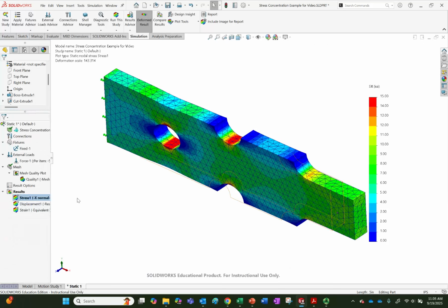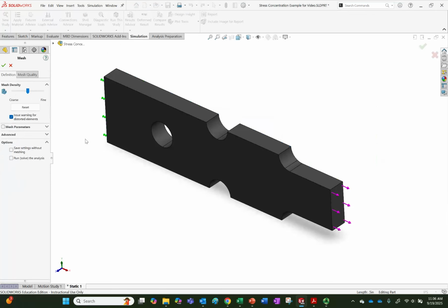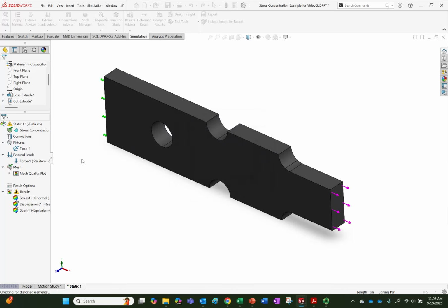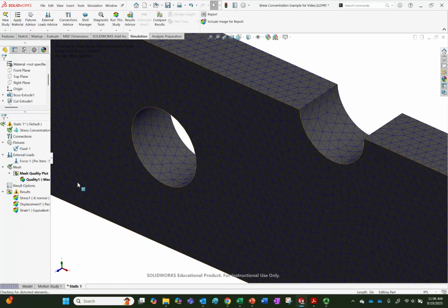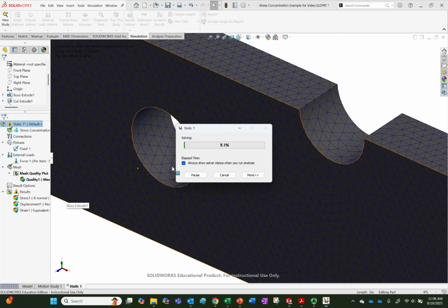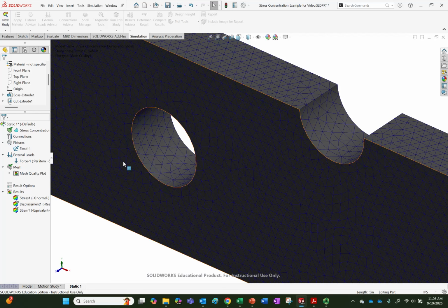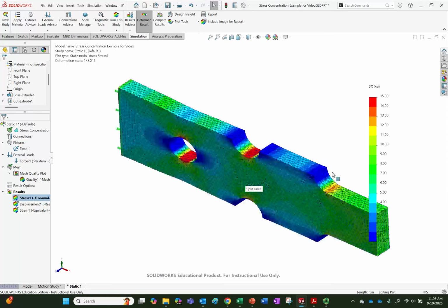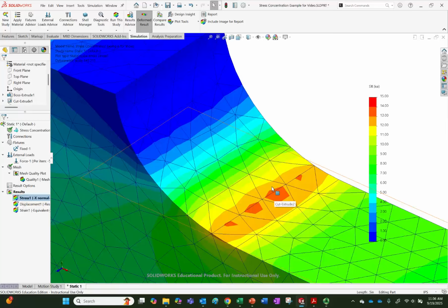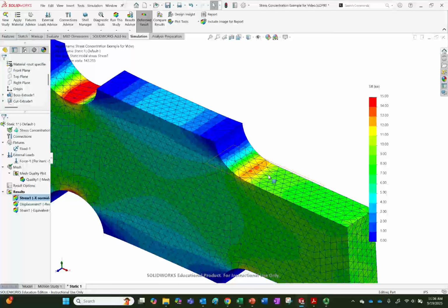So now we have to proceed with a mesh study. What we can do is, if we want to, okay, sure, is just ramp that global mesh over to the side. We can see we have a lot more nodes. Let's run it and see what happens. We should probably be recording these numbers, by the way, and then graphing them a little bit just to see how they look. But we're just looking at the results. All right, so we get a little bit better of an idea, and sure enough, you can't quite capture.